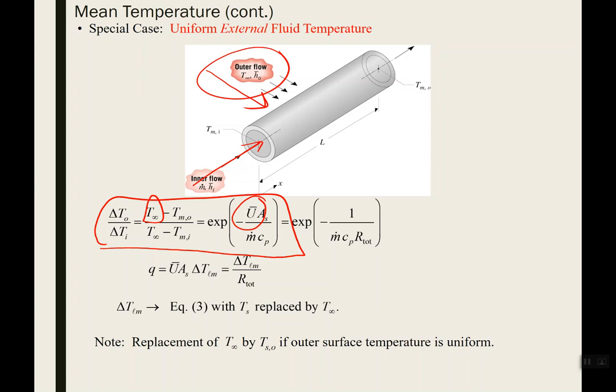So do you remember? Let's go through this again. I'll try and do this from memory if I can. So let's say we have this situation happening. We've got a pipe here, and so we've got an h in and an h out. For now, let's assume we have a thin-walled pipe, so we're basically going to neglect the conductive thermal resistance. So if we wanted to get heat from inside to outside or vice versa, how would we go about doing that?